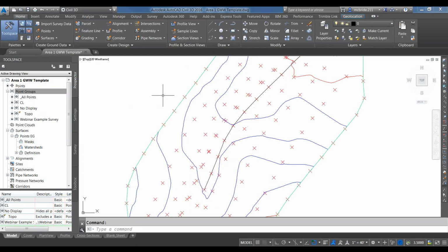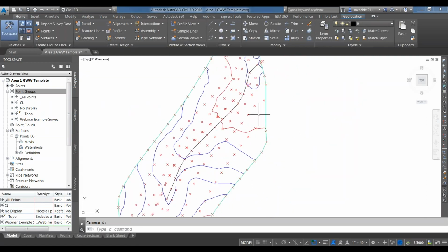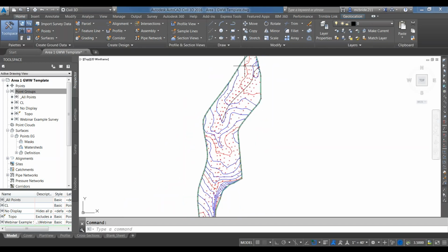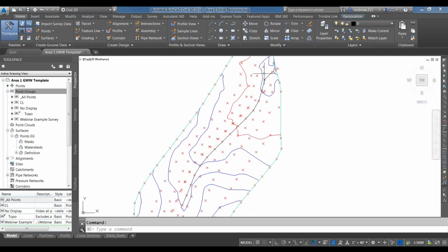It was fairly simple to do. Once they pull it out of the trailer and get it set up, they start down one edge of the grass waterway, the survey that they want to do, and they just follow this path. All of these points here on the outside are one path they travel with the Gator. They drove down and back until they got closer to the center line of the waterway. Then for the actual center line, where you have the gullies and it's hard to get a Gator into, you take it off the machine, hook it up to the post, and take individual shots down through there for the center line shots.